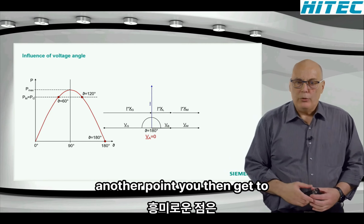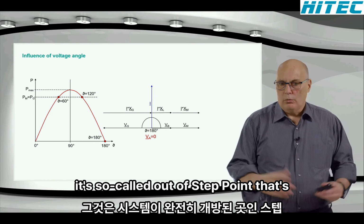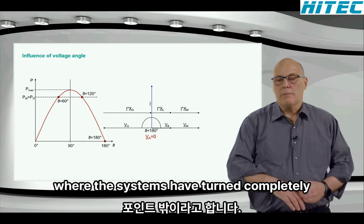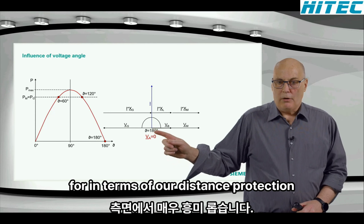Another point you then get to, interesting, is 180 degrees down here. It's the so-called out of step point. That's where the systems have turned completely open. It's very interesting in terms of our distance protection.